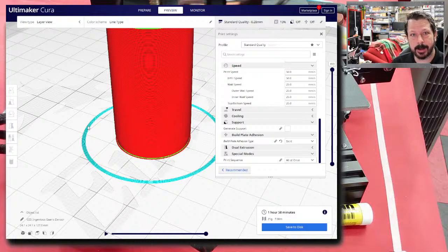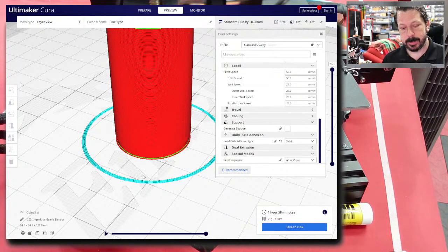I can turn the knobs on the bottom of the bed to change the level, the height of the bed, where this part is printing, based on watching it print these circles or whatever the perimeters are, before it actually prints the start print. So you can kind of tune your bed level with this skirt.